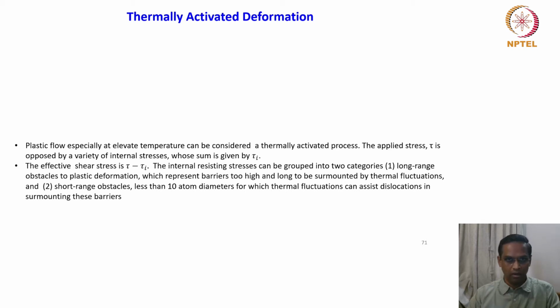In general, they don't get affected by the temperature and strain rate, except that high temperature will result in a decrease in the shear modulus of these constituents. Other than that, it does not have anything to do. The contribution of this long range stress to the internal stress in terms of shear modulus, that parameter, tau mu, we are going to see.